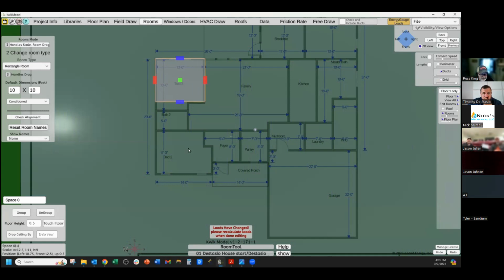And if you've got another little box there, you just place another box like so, and line it up to the walls. Then you group those two boxes together by holding the shift key and this group button, and now they stick together. So when you drag it around, they're stuck together like that. Then you just go around the house and build the house out of boxes, and it goes really fast once you get used to it.